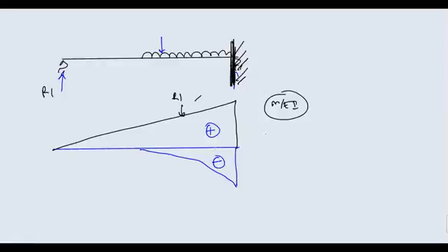So this is how you can very simply draw the bending moment diagram of any beam if you use moment area by parts. The step is simple. Just fix one of the supports and draw the bending moment diagram due to all the other forces. That is all you have to do. So I think you must have understood moment area. For practice you can solve more questions if you like. Next method that we are having with us is conjugate beam method.